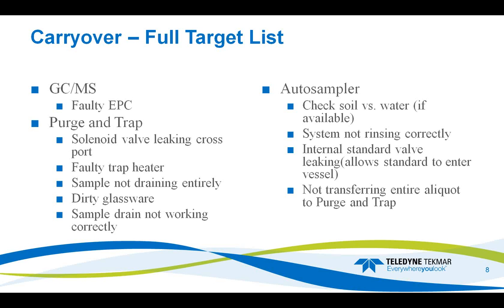And then finally, we may not be transferring our full aliquot of sample to the sparger. Again, especially with the AT100, if we don't set that pressurized time long enough, we may not completely empty that sample loop, and so whatever portion of water is left behind in the loop is going to be diluted into the next sample, and that's going to give us carryover.